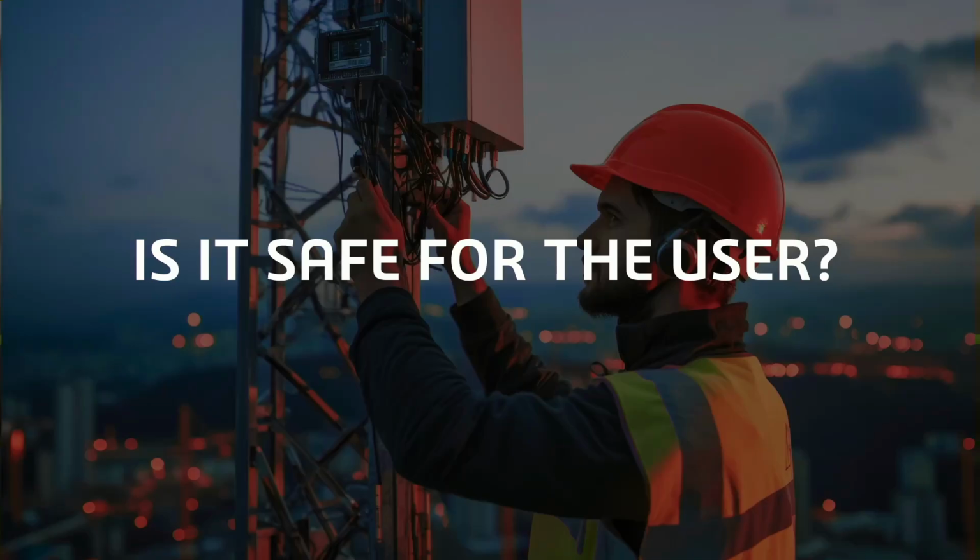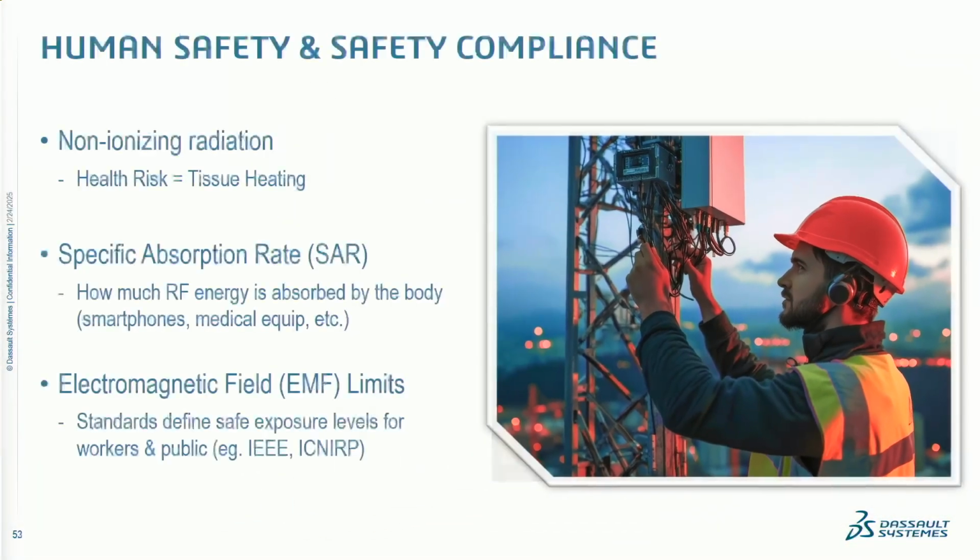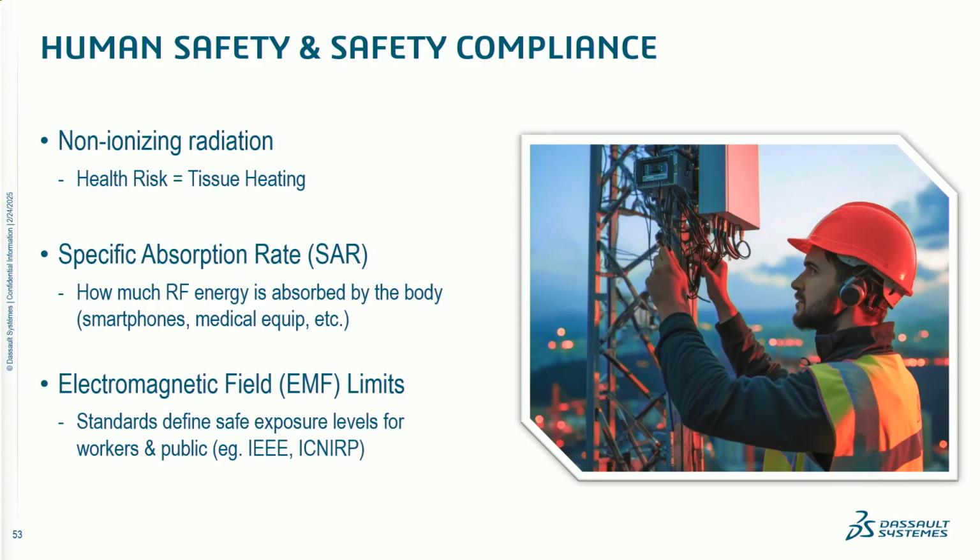And I mean, this is also regulatory, but also a little bit more important to us maybe. Is it safe? Is your design safe for whoever's using it? And what we're talking about here is non-ionizing radiation that's emitted by any electronic device. And the main risk here, we're not talking radiation like gamma radiation or things that can affect DNA. The main risk is tissue heating. If tissue gets heated when it's exposed to this sort of non-ionizing radiation, normally, and that happens when you put your cell phone up to your head, when you are wearing a smartwatch, etc.